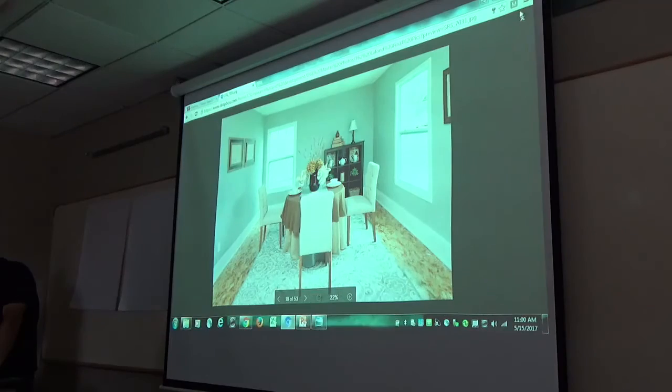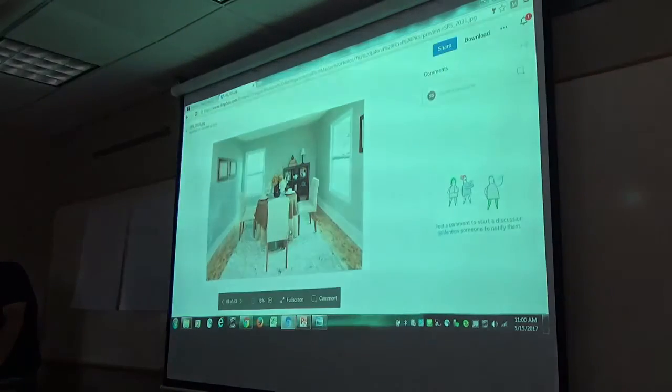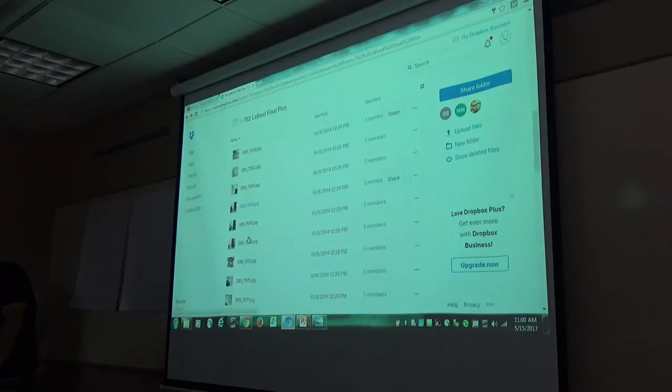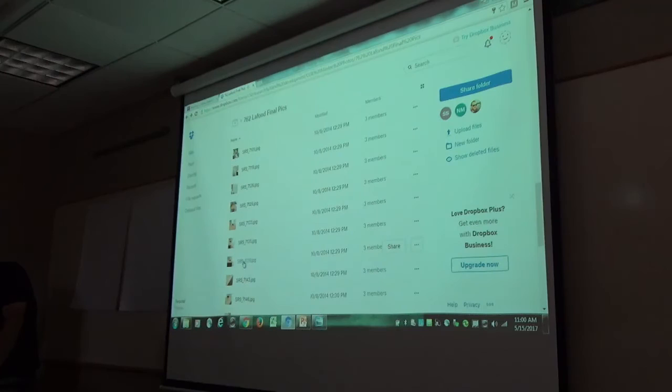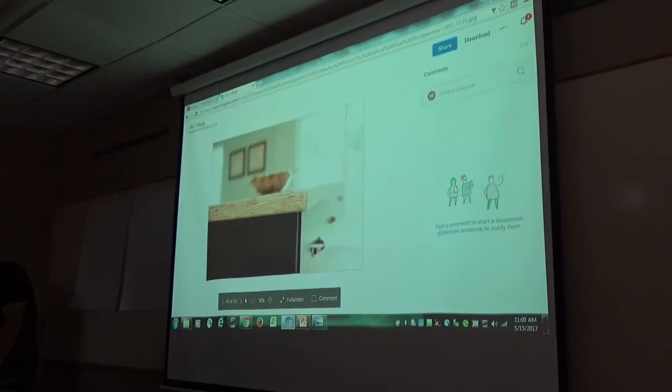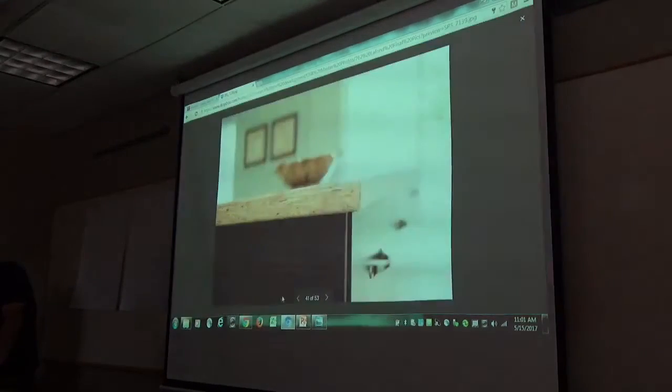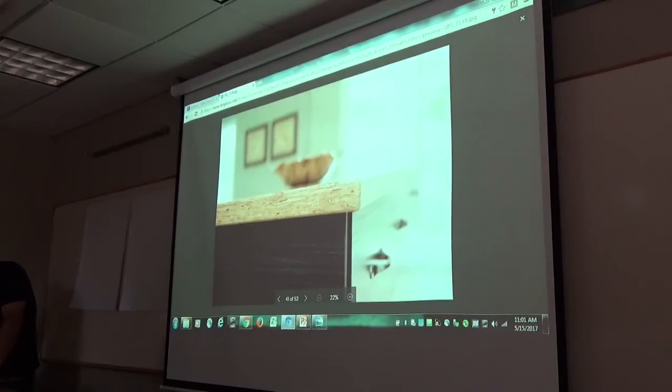I thought I had an edge picture that would demonstrate that. There it is. So you can kind of see the grain structure of this. And why I bring that up, why it's important, is because we can generate a pull-out number for an edge screw into the edge of that, which is not something you would expect even out of just regular plywood.